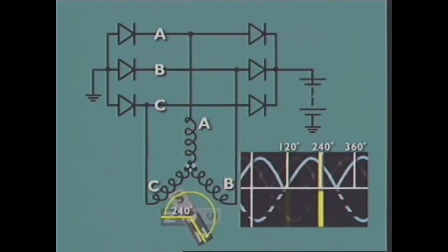When the magnet rotates further to this position, the polarity of winding A changes. The current path then is winding A at star point, winding C, positive diode C, alternator terminal B+, battery positive terminal, battery ground, alternator ground, negative diode A, and output of winding A.